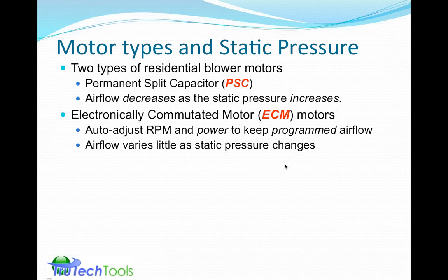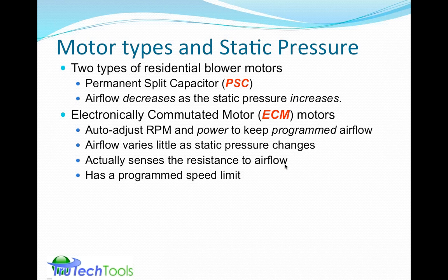So the airflow actually varies very little as the static pressure changes, and the motor can sense, I believe it's usually through the torque that's going through the motor, the resistance to the airflow, and it knows it has to pick up speed in order to achieve the specific CFM. They sometimes have programmed speed limits, so they don't run out and destroy themselves.